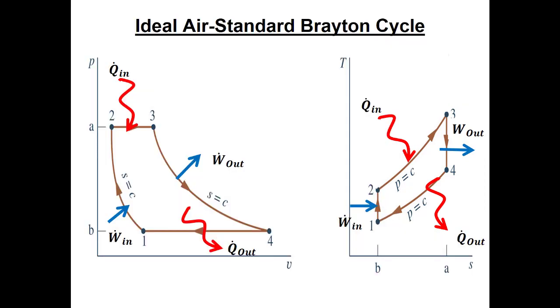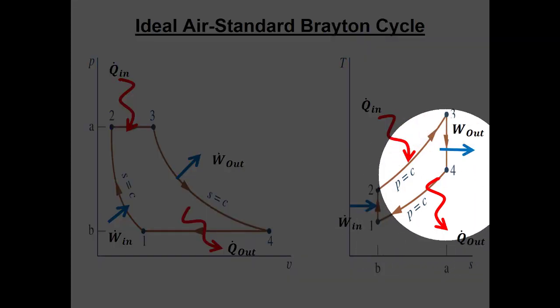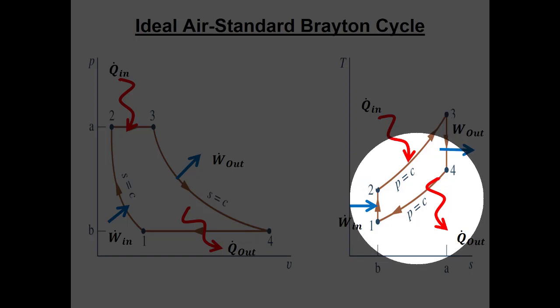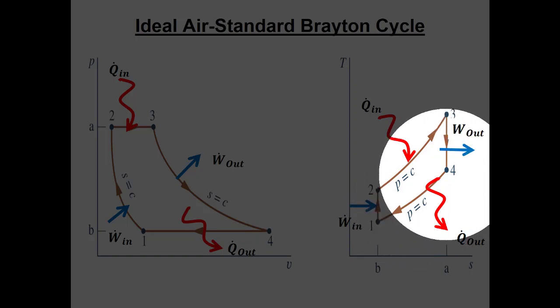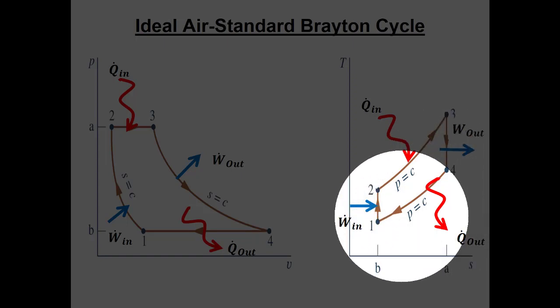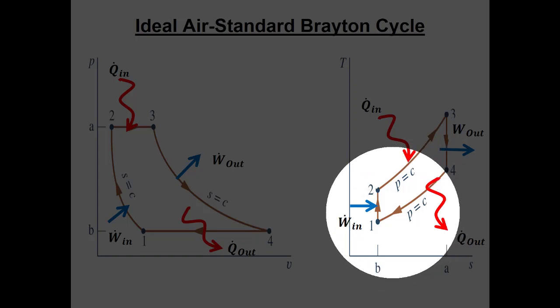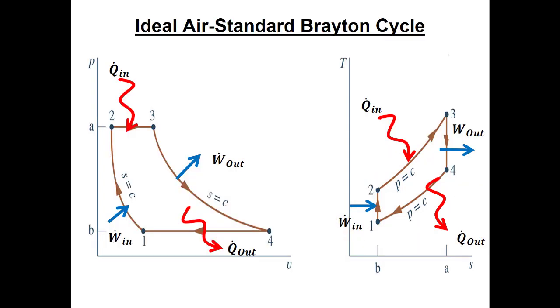Then we model this system by putting a heat exchanger between state 4 and state 1, even though we don't actually have a component here. Really, what happens is we exhaust this exit fluid from the turbine into the atmosphere, while at the same time pulling in air from the atmosphere at state 1. So that means we can sort of model this system as if there's another heat exchanger there, where that heat exchanger is the environment.